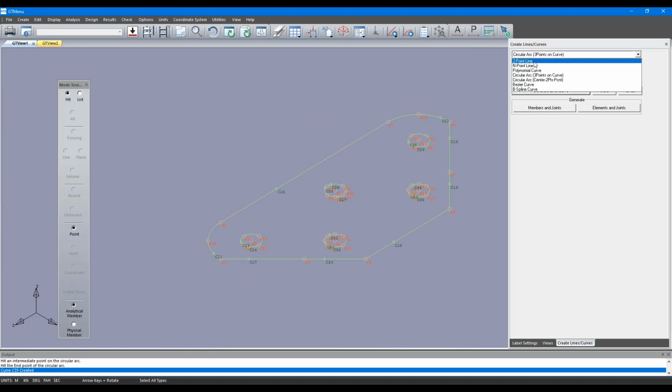Those boundary lines are basically lines connecting these circles that I've drawn, and let me show you how that looks. This is a first boundary line, and on that boundary line I'll be able to control the mesh density along that line. So if I have to attach, let's say, a stiffener plate to this plate, I have an edge to connect to. Okay, so we're done with the hard part.